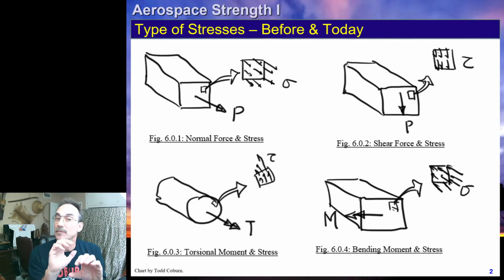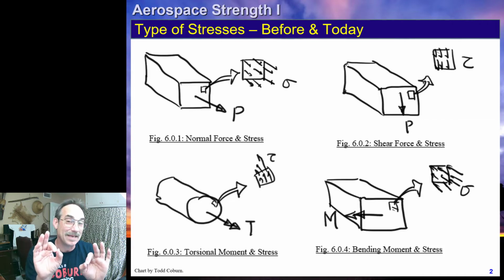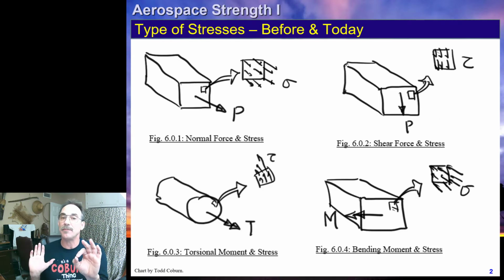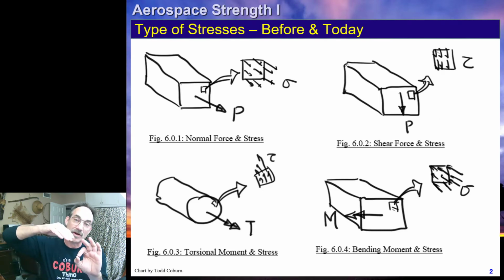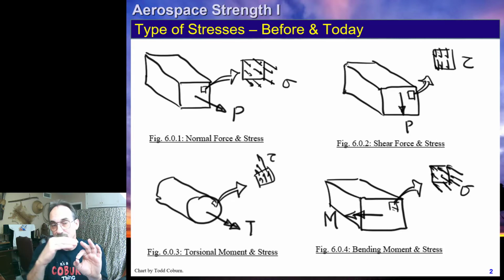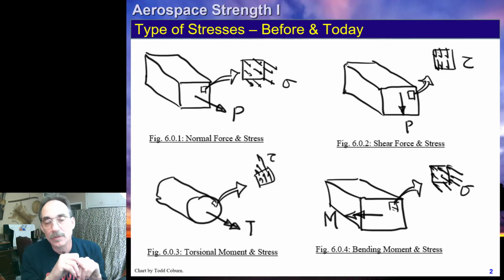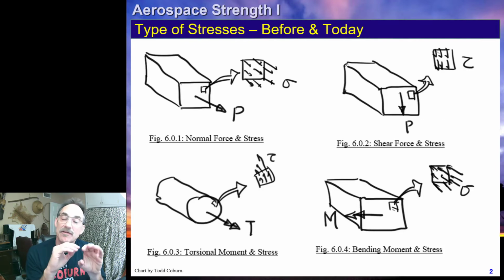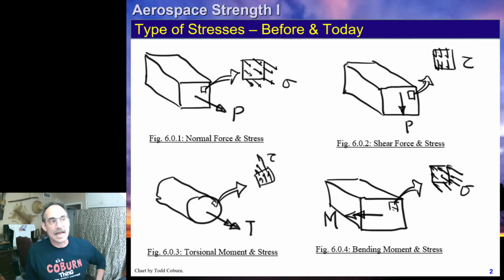And for this kind of bending moment, which would be a positive bending moment for beam sign convention, we're going to see we go from a positive tension at the very bottom to a maximum compression at the very top, where the stress distribution and the strain distribution are linear from bottom to top. And if we take a look at any little point on the section, we're going to see that stress is a function of its position relative to the centroid or neutral axis. This is what we're going to be studying today and investigating how those stresses are calculated.